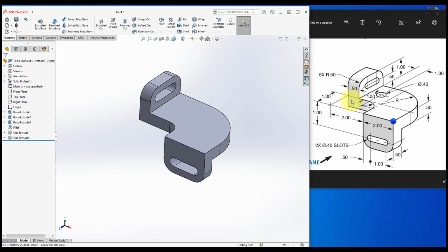And the last thing is to put this circle in, and I think this dimension is either drawn incorrectly or it's distorted somewhat, because if this distance is 1, you can see that the distance coming out here really cannot be 1. So this line, this extension line, is implied that it's going to the back. However, in that case it would be in line with this one. So you can see there's a distortion. So I think that's a drawing mistake because I've tried it, and if I put that dimension out to being 1, it doesn't quite look right.